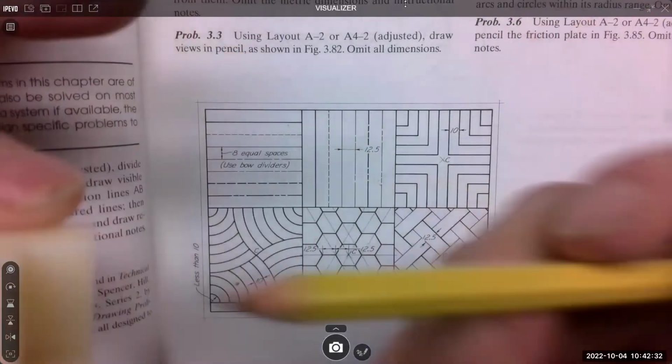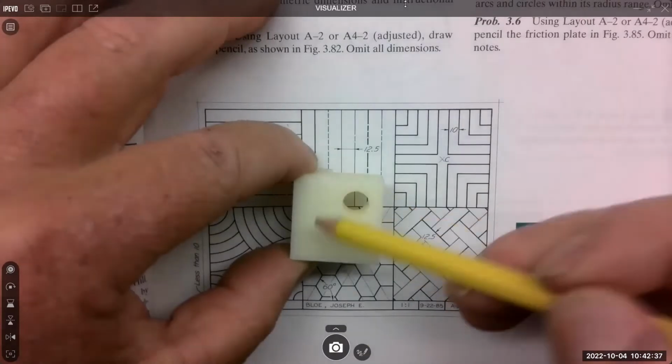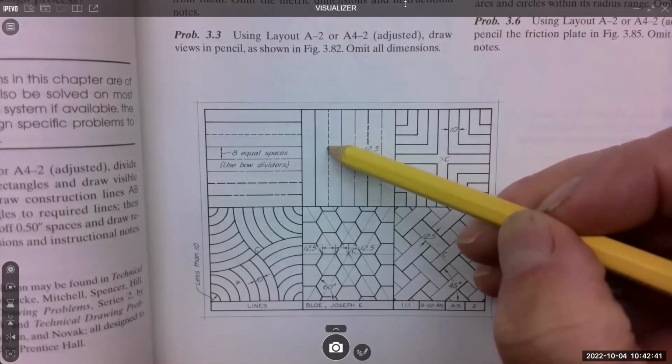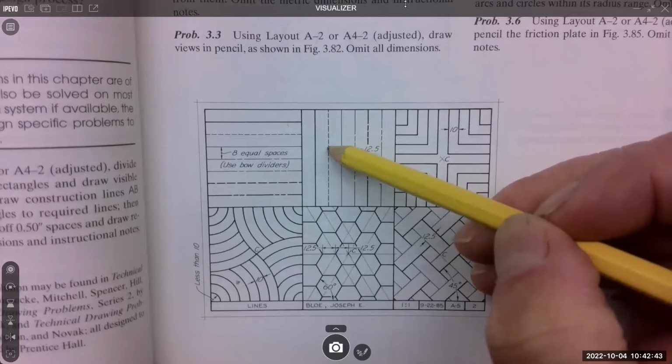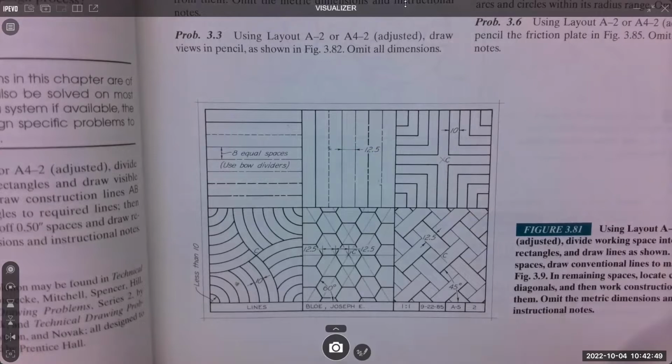But back here in the back, I can't see that edge and that edge. So that would be hidden. And this is a hidden line, and hidden lines are thin. And I don't care how thick your thick lines are or how thin your thin lines are. All I care is I can tell the difference. Like, oh, that's clearly thick, and that's clearly thin. That's all we need.